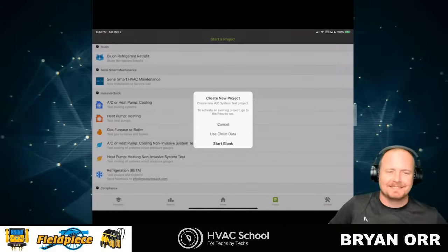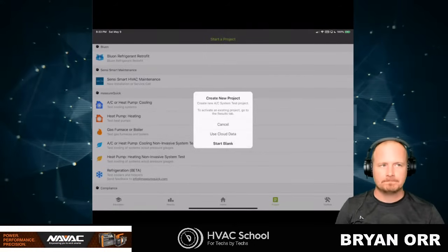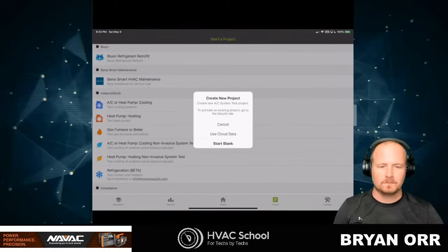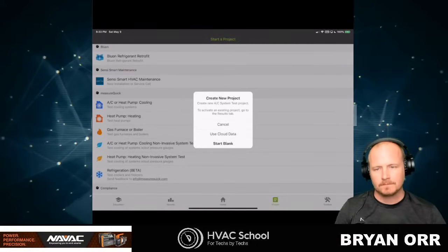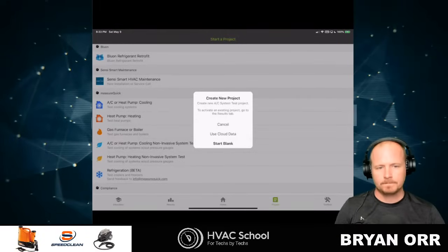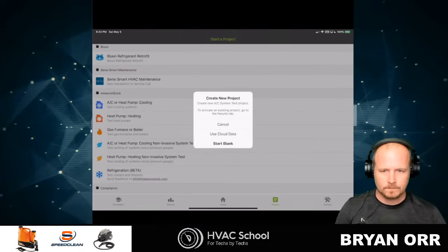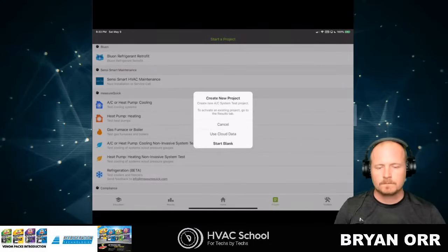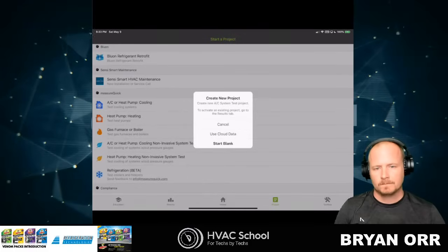I said if there's nothing wrong with the system, so it's clean and the filter's good. I'm just saying that to go through and actually retest the system takes almost no time at all. And once you have that benchmark in, the diagnostics are really accurate, because we know exactly where the pressure should be. So we know what's high, we know what's low, we know if things have drifted off.